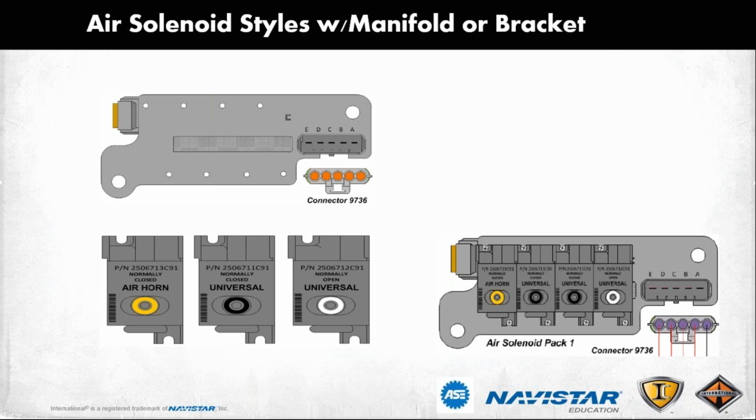On our trucks, we use 2 of these side by side for an air suspension dump. In between those 2 solenoids with the white rings, they'll have a little shuttle valve that shuttles back and forth. We use those, like I say, to raise and lower the air suspension. So these are directly hardwired to the body controller. They have a common ground. There's 4 high side drivers coming out to control these.